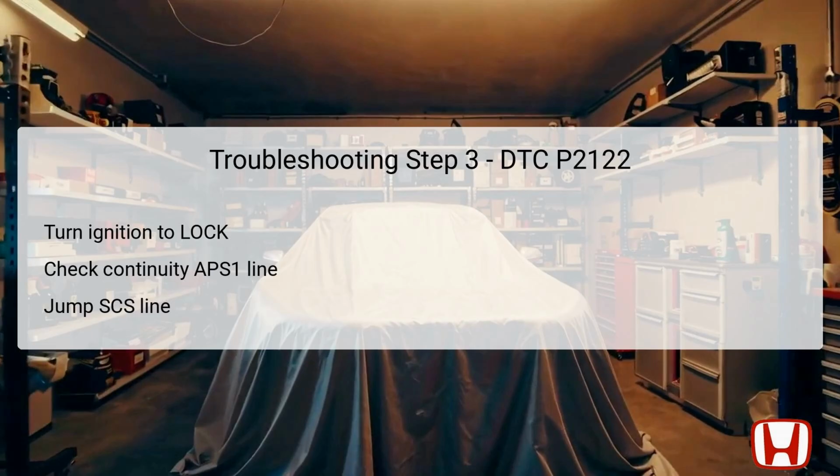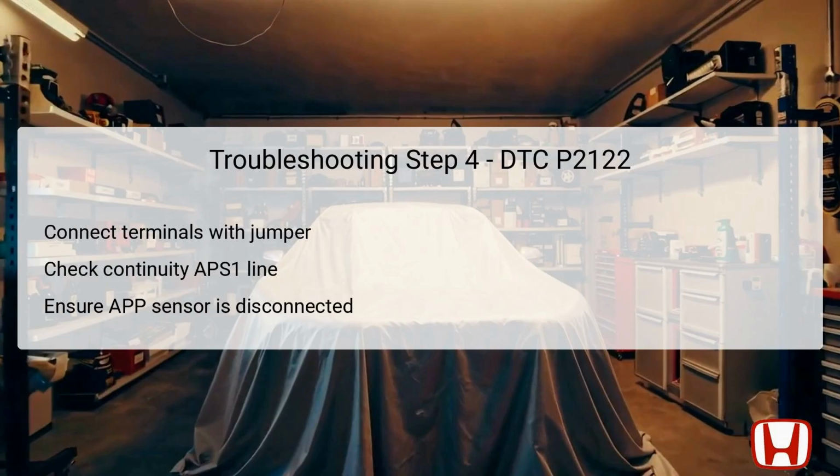If there is continuity, this indicates a short in the APS1 wire between the ECM and APP sensor, necessitating repairs. However, if there is no continuity, this suggests that the APS1 wire is intact, allowing you to proceed to step 4 for further investigation.